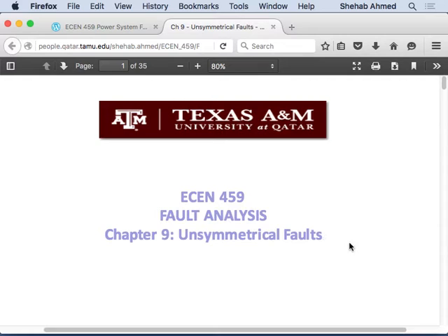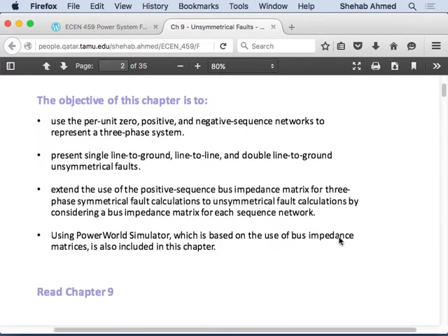So how do you analyze those? You have to utilize symmetrical components. Faults are a good example, and the biggest reason why we study symmetrical components, because we want to understand how to protect the system. How does the system behave? So I can place the current and voltage sensors in the right places. That's really the objective of what we're going to try to do here.